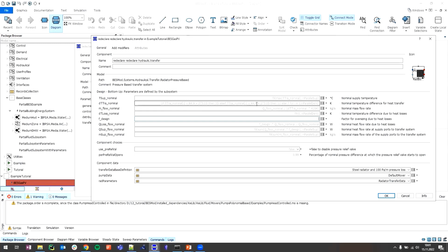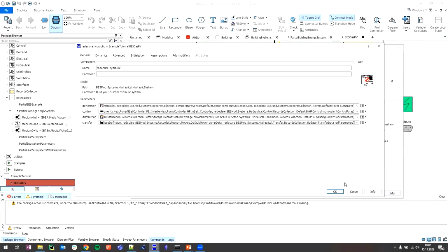If we are higher than 45 degrees Celsius, we use 10 and else 7. These are typical values for radiators, and 7 is for underfloor heating. So based on the temperature level demand you have, you can trust that these nominal values are according to standard. You can change it if you want, but you can go with the default for a start.